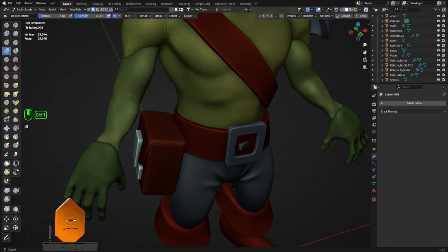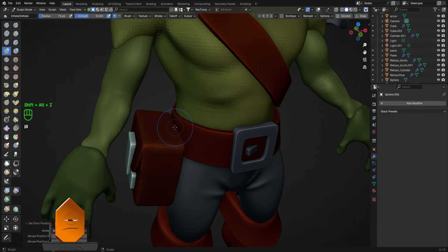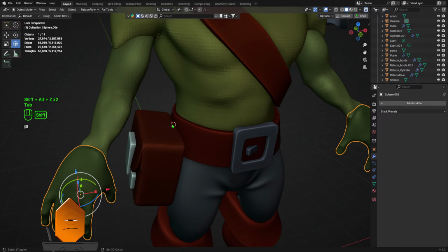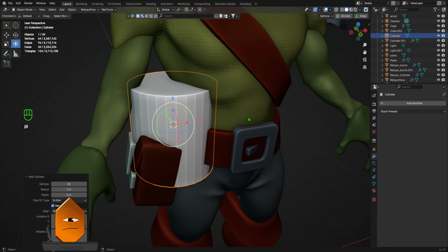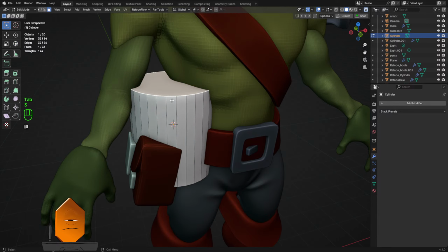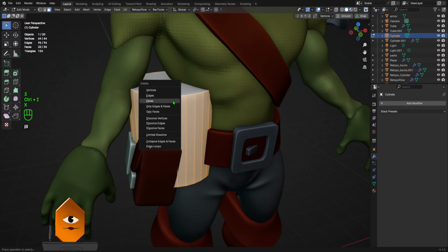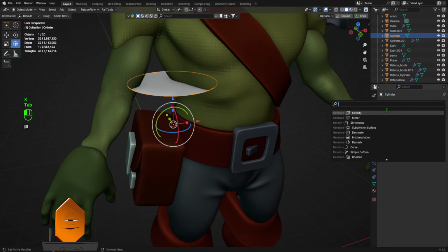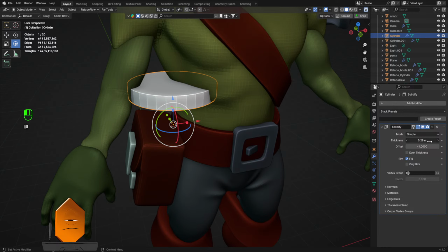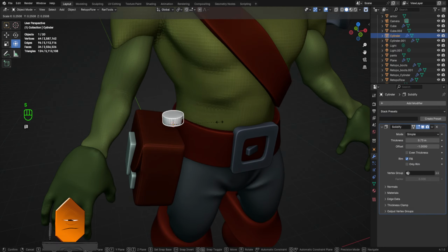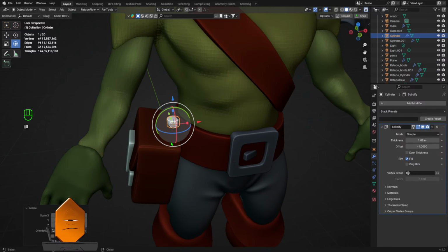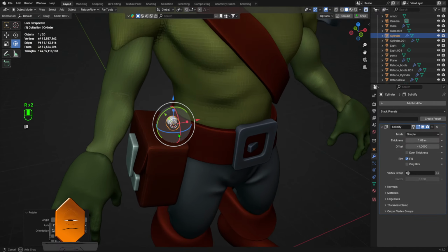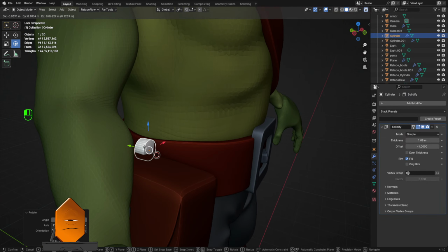How do we want to attach this? Let's do something very simple. Go to cylinder. Gonna grab this face, Control I, delete the other faces. Add modifier, solidify. Something like that. Maybe a bit thicker. RY90, RZ90. Yes, I call it Z.